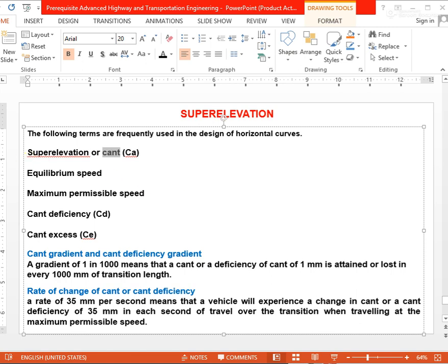So for that purpose this maximum permissible speed is coming, and for this maximum permissible speed lots of factors are involved: radius of curvature, actual super elevation, cant deficiency, cant excess, and length of transition curve. On curves where the maximum permissible speed is less than the maximum sectional speed of the section of the line, permanent speed restriction becomes necessary.